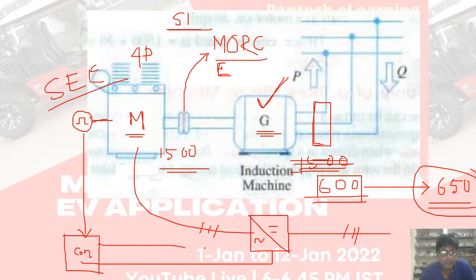And from the control you have to give one feedback to the overrun clutch also. You can take an electromagnetic clutch, it is always better. Normally it will be de-engaged, and when the supply goes, the clutch will be engaged.